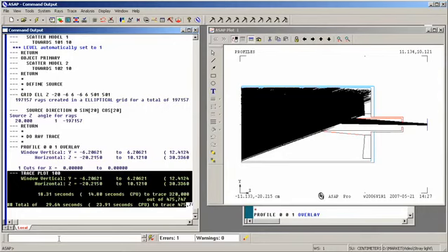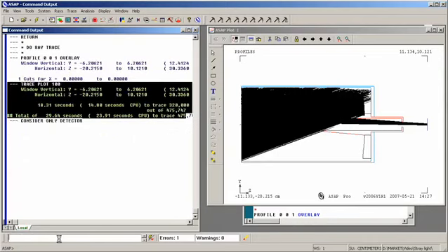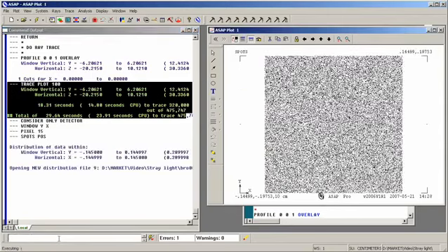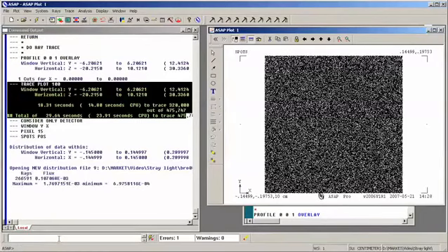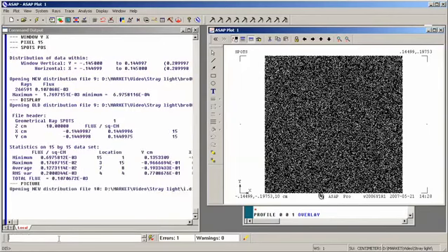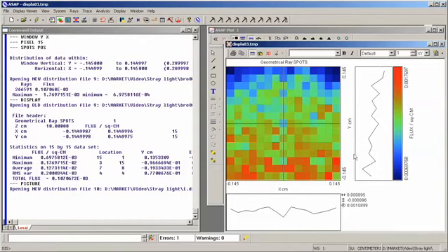Okay, we can now do exactly as we did before to calculate what the stray light irradiance is. Consider only detector, window YX, that's the size or dimensions or axes of our window. Pixel 15 is the resolution of our plot. Spot position gives us our spot diagram and also calculates the stray light irradiance. The display command reads the file, and the picture command makes a picture of it. And so this is our stray light irradiance on the detector.